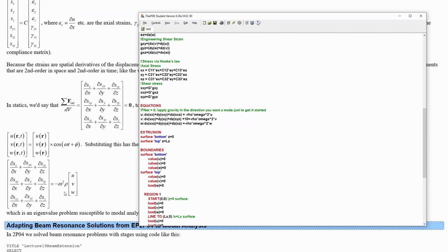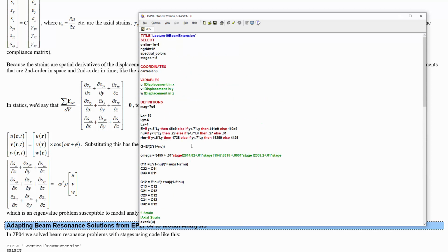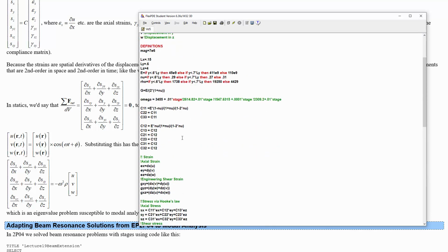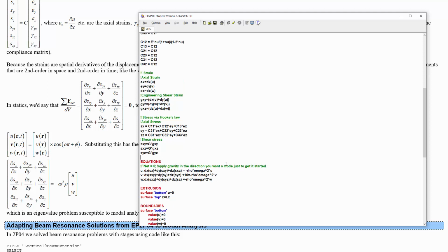So we're incorporating this eigenvalue version of the problem. In the statics part of the course, we just had this equal to 0 every time. And then in the resonance part, we said that this is equal to negative rho times omega squared times u. And then what we did is we kind of manipulated the finite element method system of solving the problem by telling it to just try a bunch of different omegas and look for where we can get the biggest displacement, and then said that's probably a resonant mode.